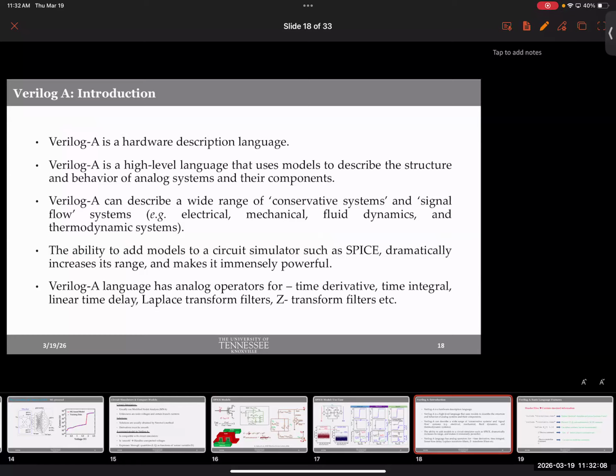So that's where Verilog-A comes in. So there are some unique advantages that Verilog-A brings, and from now on, we'll only discuss Verilog-A, right? We'll not really pay too much attention to SPICE-based modeling and others. Okay, so Verilog-A is an HDL or hardware description language. There are other hardware description languages that you may have learned, right? Remember, don't mix it up with conventional Verilog. Okay, Verilog-A and Verilog are not the same. Okay, that's something that people often misunderstand.